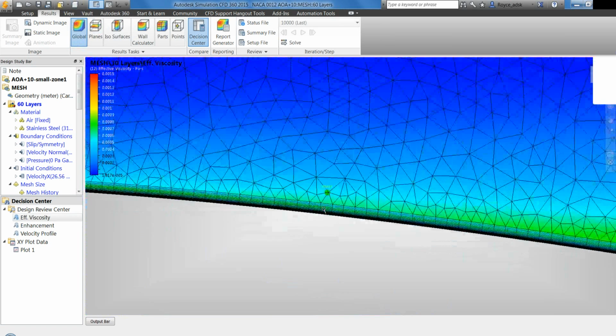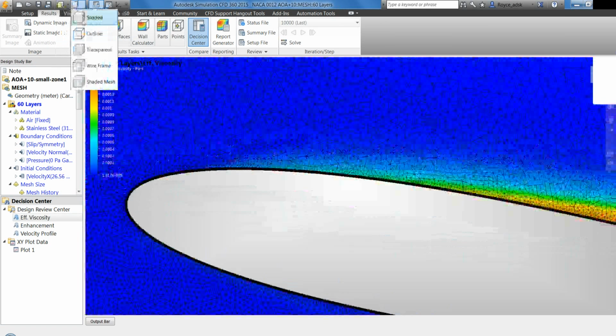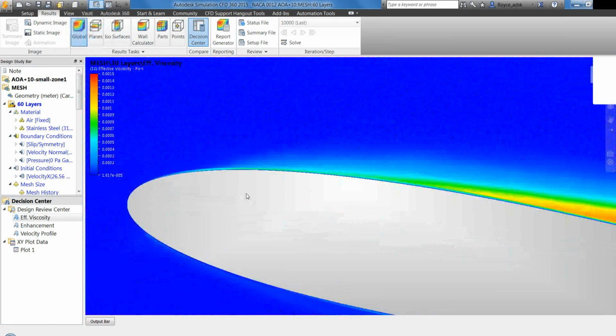And from there, that's where the solver takes over. Okay, so in terms of turbulence, it's more critical that you get the mesh close to the wall as possible to capture the nonlinear portion of the boundary layer. And from there, it's really just controlling the transition to get an appropriate mesh. Okay? Any questions out there?